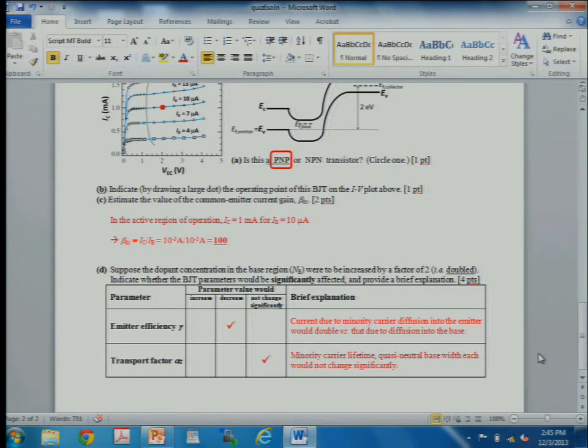But in practice, yes, sometimes more heavily doped regions have lower minority carrier lifetime because the process of doping causes more damage. So it's not inherent that the dopants cause that smaller minority carrier lifetime. It's just that the process results in more defects.